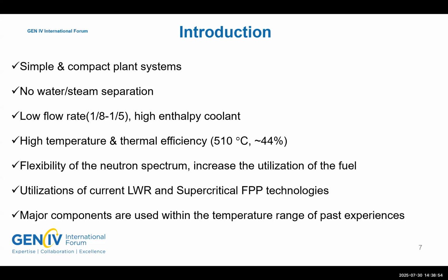44%. And you see that the density of the supercritical water decreases when the temperature crosses the critical point. So the flexibility of the neutron spectrum can be realized, because if the density is decreased, you can design your reactor with a faster or thermal spectrum.